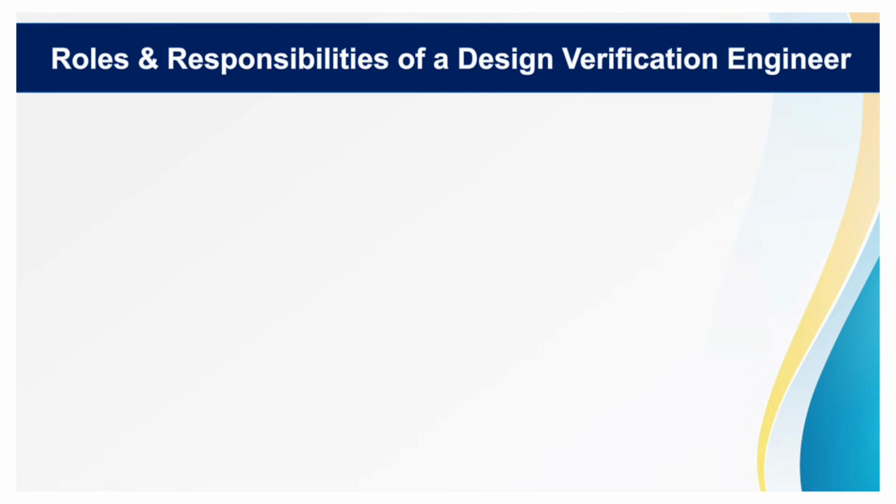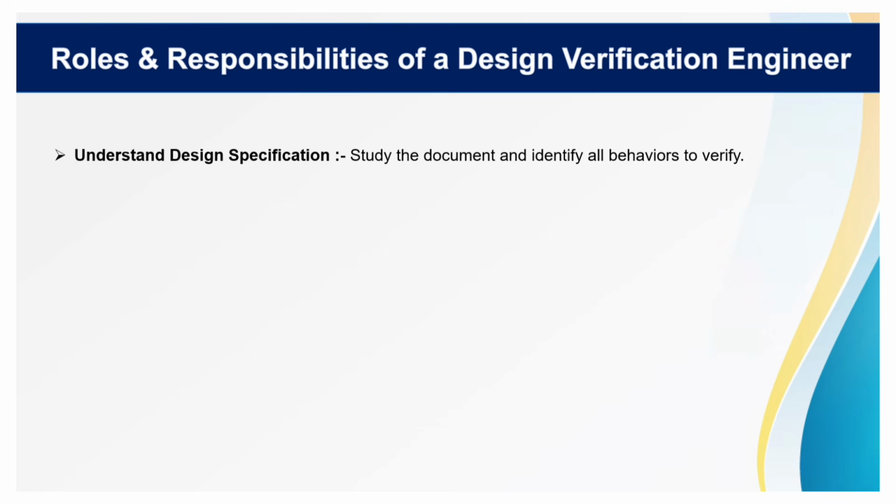Now let's talk about the roles and responsibilities of a design verification engineer. Many people think that a DV engineer simply writes some test code and runs simulations, but in reality, their responsibilities are much broader than that. The first and most important responsibility is understanding the design specification. Every hardware block comes with detailed documents that explain how the design is supposed to behave. Before starting any verification work, a DV engineer must carefully study these specifications and clearly understand all the expected behavior of the design.